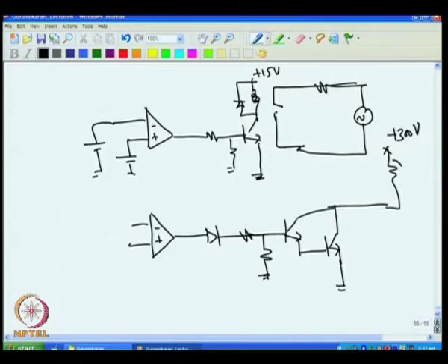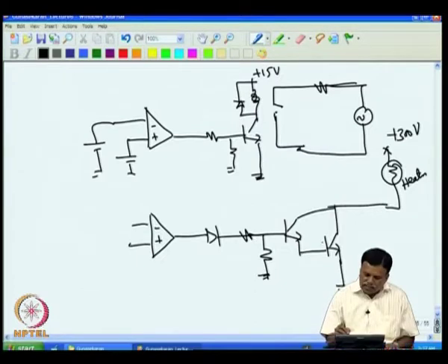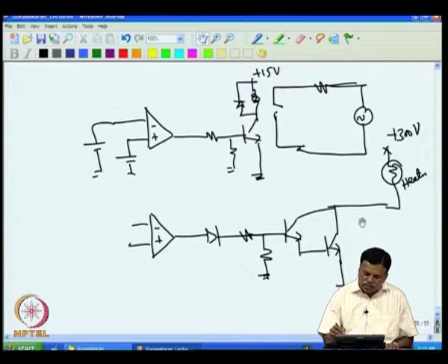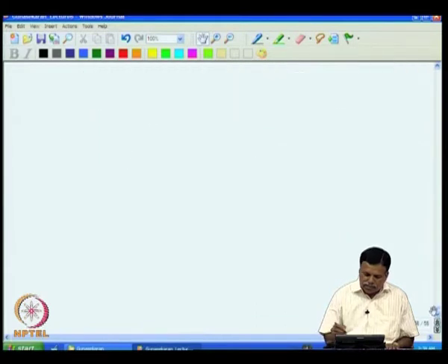So, this can be a heater and this can be high voltage and high power, because now even the 15 volt coming here can switch this on, and this voltage can be even 300 volt or any amount of voltage. The only condition is that this transistor and this transistor should withstand the VCEO breakdown, then only this can work. So, this is easier to write, or we can also use, for example, a thyristor.